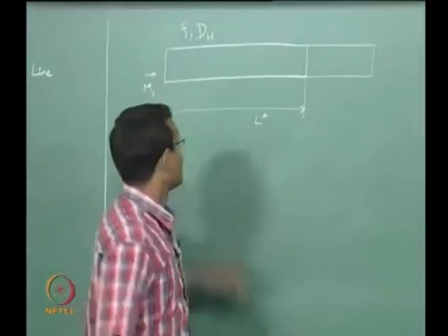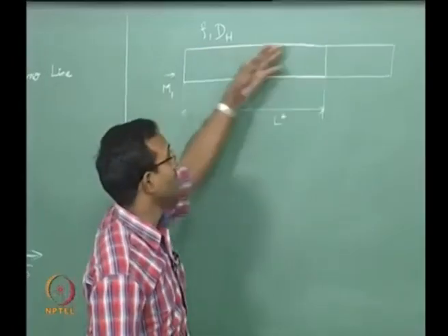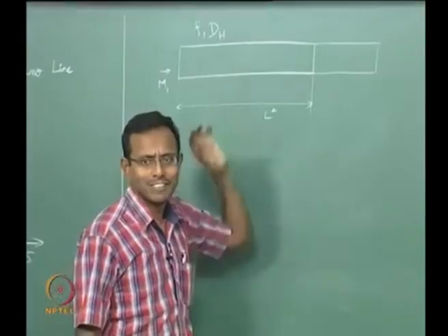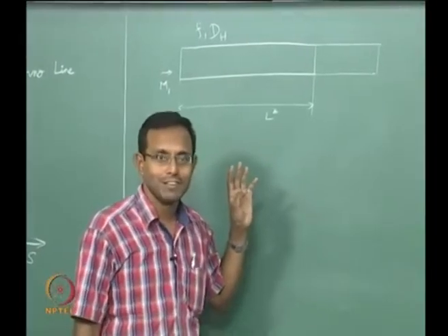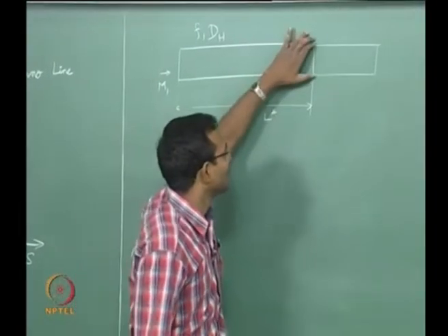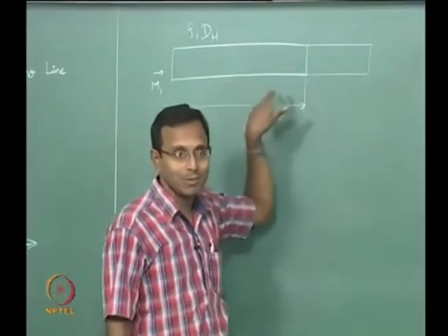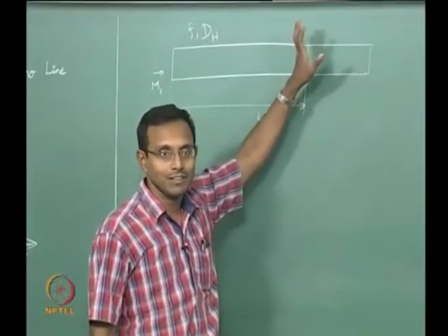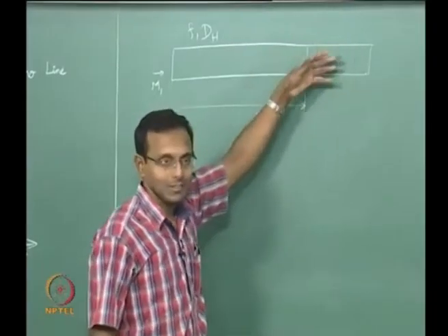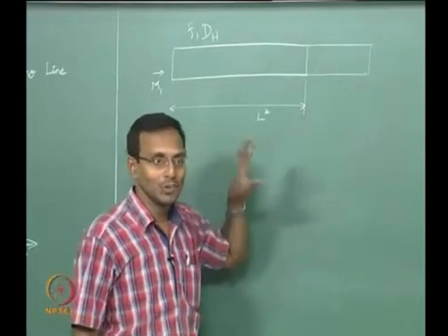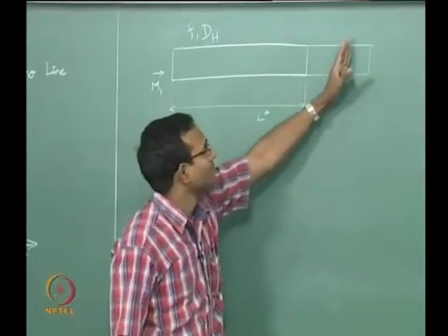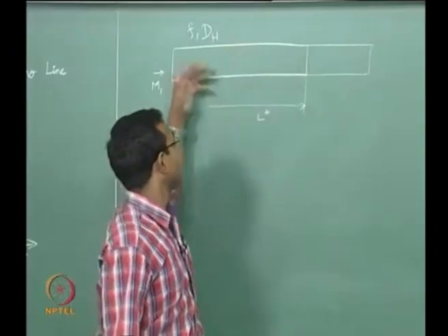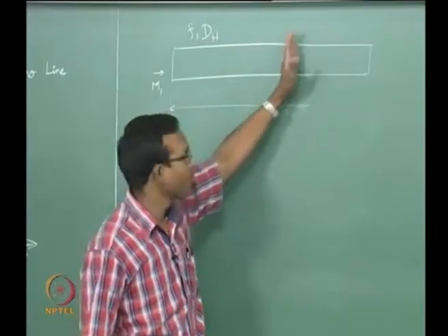Okay. If it is subsonic flow and I am sending compression waves inside, what will happen? Compression waves always travel at speed of sound. What should happen? Say I just introduced this length L, all the same it was not there, I just added this small tube extra on this. Now the flow has to go through this. From that time t equal to 0, when I added this, there is going to be a set of compression waves that is trying to go in. What will happen? They are going to go faster than this flow. They will keep on going in.